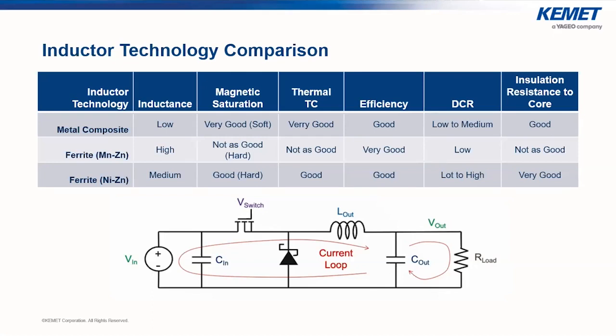And then the second thing is that inductors have this thing called saturation. What will happen is that the material saturates, and it's no longer able to amplify the magnetic field as your current increases. And so therefore what happens is you'll see your inductance sit at a certain level, and you hit a certain current, and then your inductance will plummet. And at that point, your inductor is not going to be usable in the circuit. I mean, it's still going to operate, but it's not going to provide the inductive performance that the circuit is requiring from it. So saturation is a big issue, and saturation of materials tends to be temperature dependent.